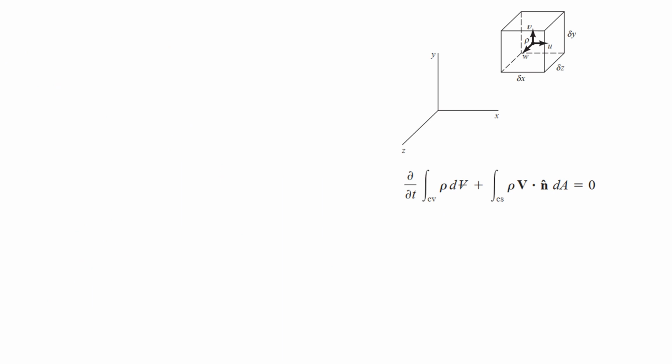So in the previous slide, we derived a differential term for the change in density inside the control volume by using this term of the Reynolds transport theorem. So we derived a term that was partial change in density with respect to partial change in time inside a particular control volume, and this was our control volume, this cube right here. Now we are going to derive the differential term that will be the mass rate of flow across the control surfaces, that is represented by this control surface.